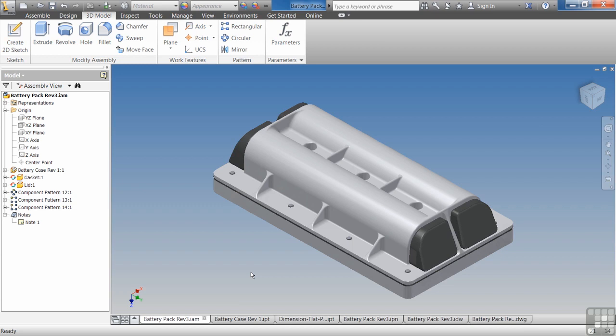If I put something in after it's fully assembled, then that's where I need to put it. I need to put it in the assembly because that hole does not need to exist. Now, if you just need it for reference, if you just want to see where another hole is in another part, you still do that at the part level.